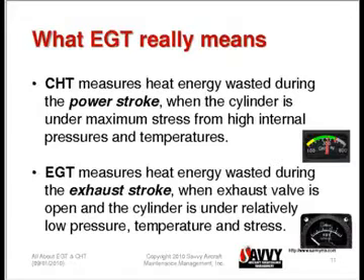And we'll see this a little bit later in another graph, but basically what CHT is telling us is how much stress the cylinder is under. It's not measuring it directly in pounds per square inch. It would be nice if we had peak pressure gauges mounted on our cylinders. They do that sometimes in test stands, but we don't have them in the airplane. But CHT is the best proxy that we have for how much stress the cylinder is under.